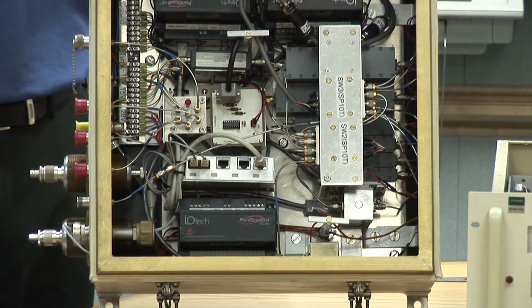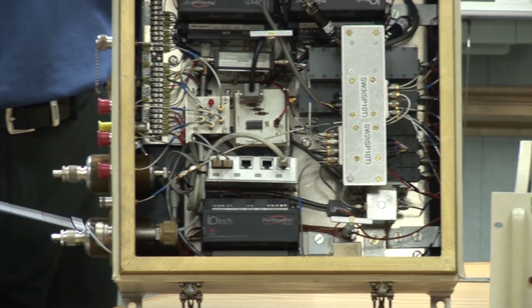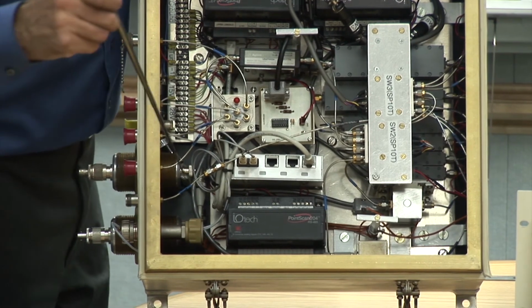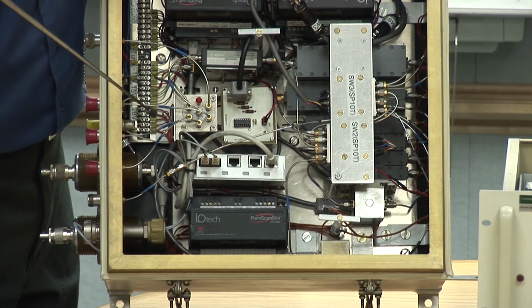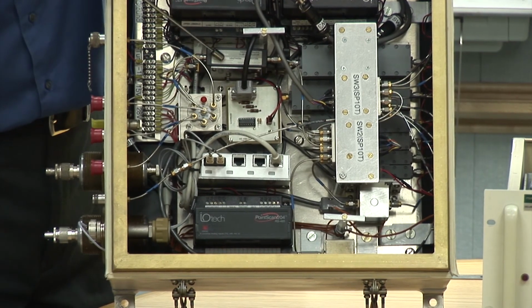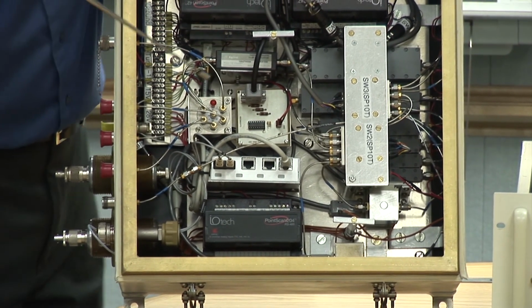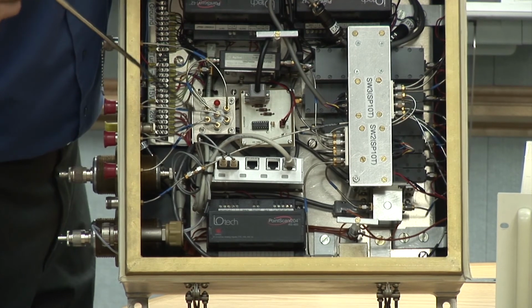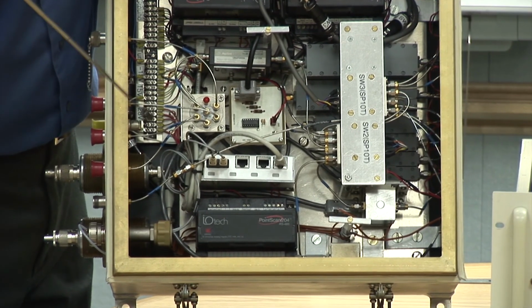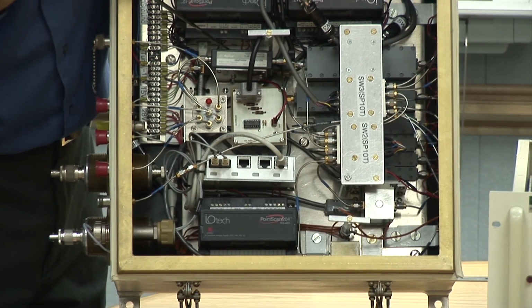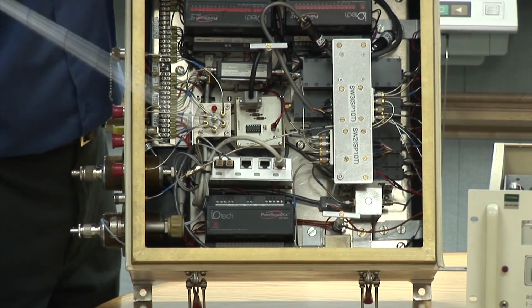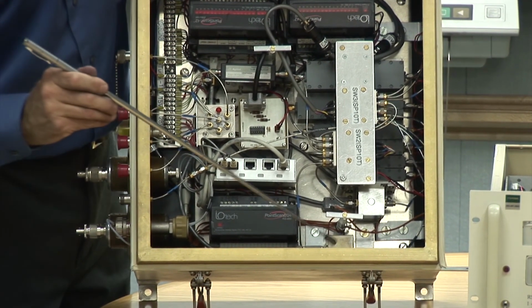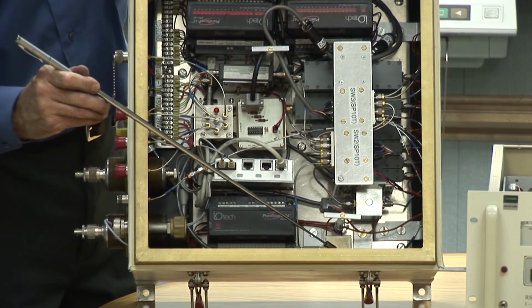Here we have an RF input port, a couple of RF input ports. These come into front-end relays, which switch us into an attenuator here, first of all. And we also have a noise diode at the front end, which is used as a calibration source. The noise diode is right here behind the attenuator. Then, coming out of the attenuator, we go into the YIG filter section. Here's the YIG right down here.